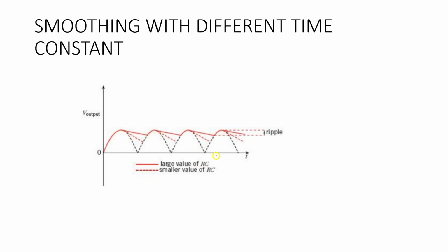So if I increase RC to another level, you could create another curve right here and get an even more perfect output. You understand? Looking more like this, to say that it's going to look closer to the peak rather than having gone all the way down. You could use a much higher RC value to get a more steady wave. You understand? So that is really what is happening here.